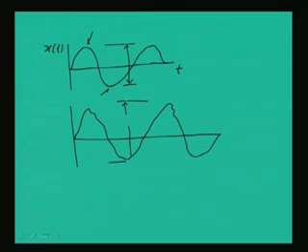So, this is the total displacement, because this peak to peak value gives the displacement of the machine surface or machine structure. So, obviously, they are related with the stress which they are undergoing with respect to time. So, they are reflecting in a direct way the stresses. So, these are very important.